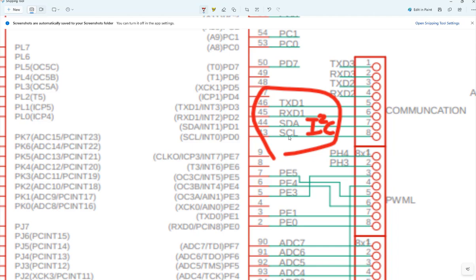If people in the interview ask you, what's a good interface or communication port for SD card? If they ask you, can you use UART or I2C for SD card? The answer is no, because an SD card usually has gigabytes of storage, and I2C and UART are so slow. There's no way that I can use I2C or UART. You have to use SPI, right? So SPI can run up to like 2 to 4 megahertz, and you are able to write and read a large amount of data from the SD card. So I have to use SPI.